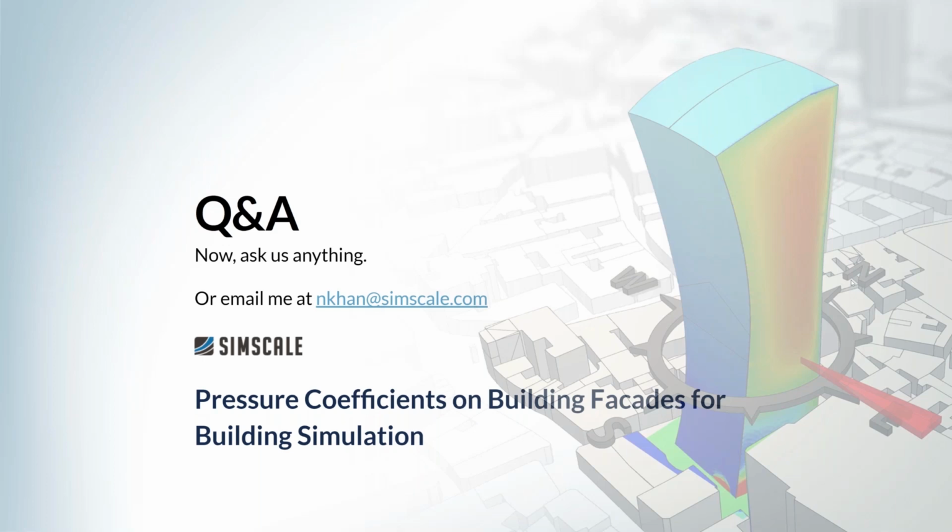Is the building modelled as a rigid obstacle, or is the building flexible and captured through fluid structure interface? SimScale doesn't support fluid structure interface at the moment, so this is completely rigid, and obviously we're not taking any fluctuations in terms of building movement into account. So we've done a transient analysis on a rigid structure, and we've averaged the results over time to obtain these average results.